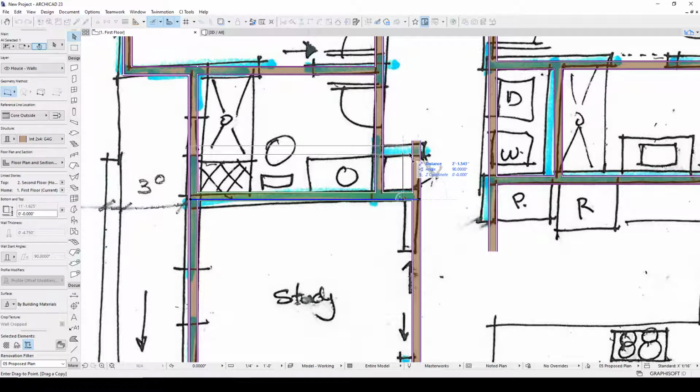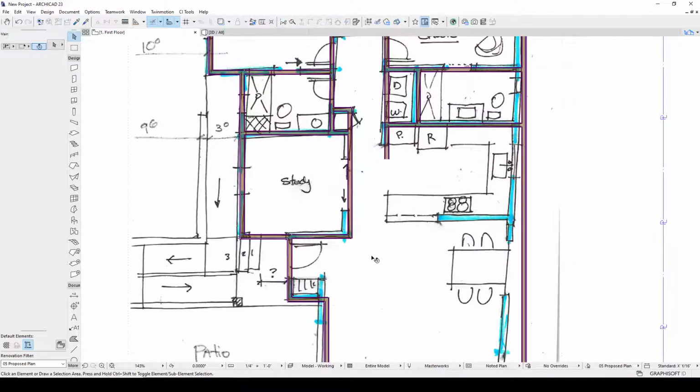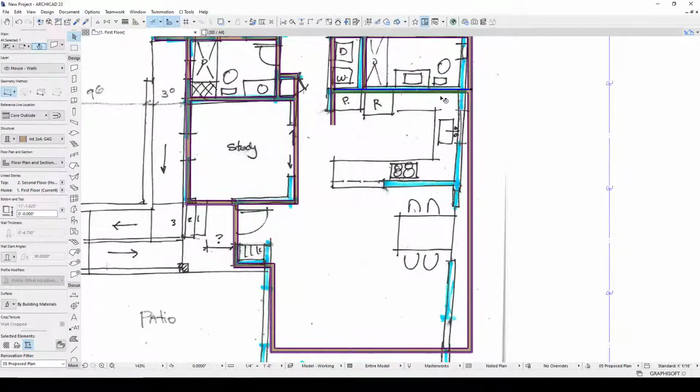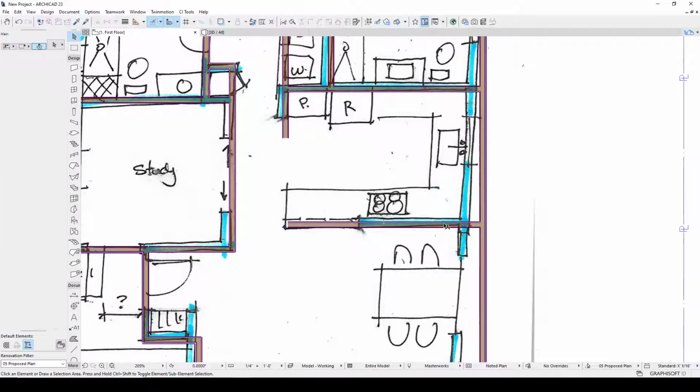F9. We'll go 2'3". Make sure it's a wide enough closet. Select those. I for intersect. Trim that with control. And here, we'll do an even 9 feet there.